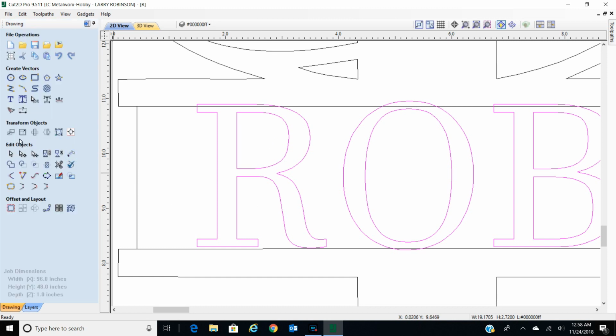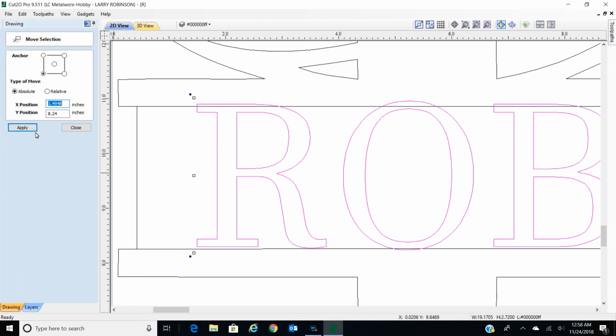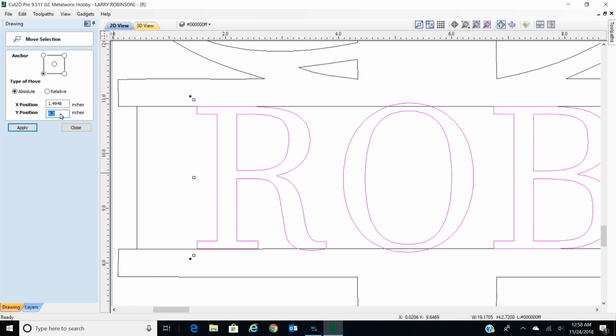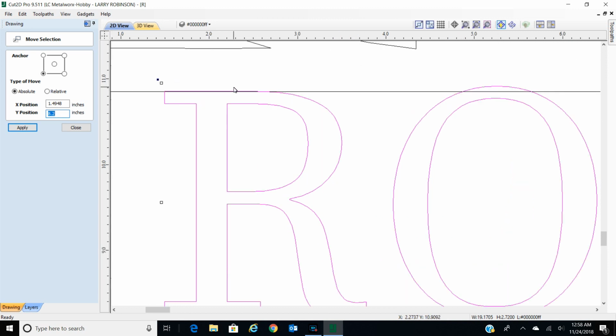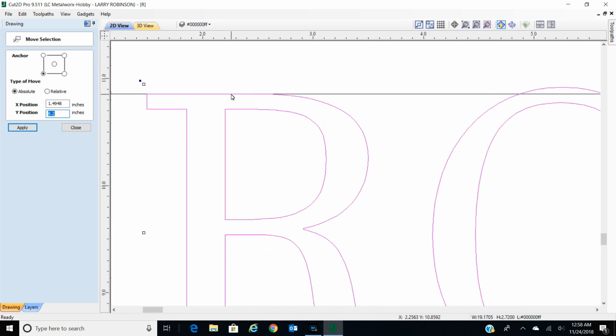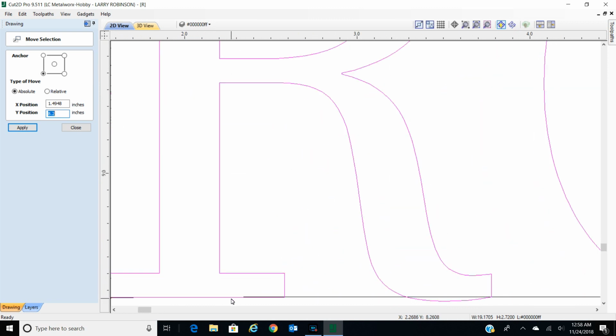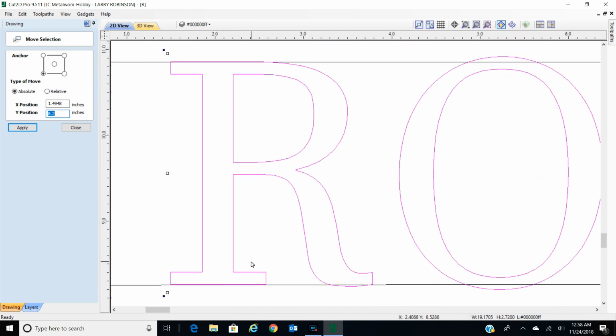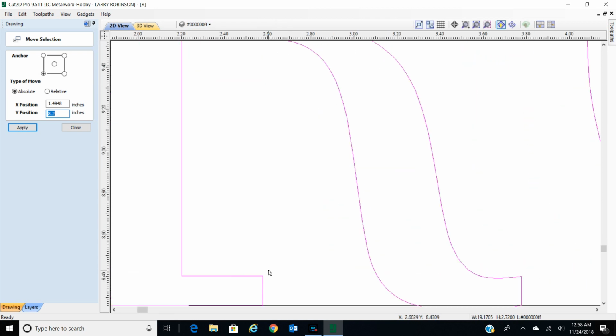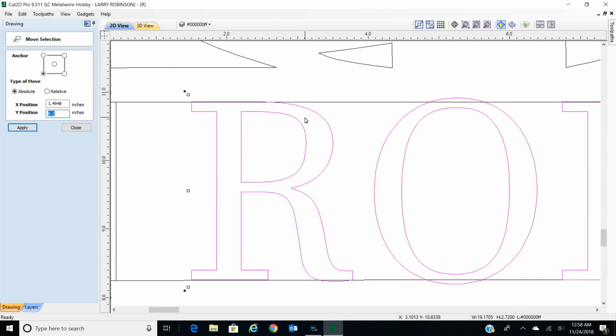So let's close that tool. Go to move. This is our X and Y coordinates, so we need to move the Y to a little less, more negative from what it is, so let's just go with 8.2. Zoom in a little. We need these to just clear that box. And it needs just a little more on the sides, but I think we're about right on our up and down. Now these curved letters take a little more adjusting, but we can work on that in a minute.